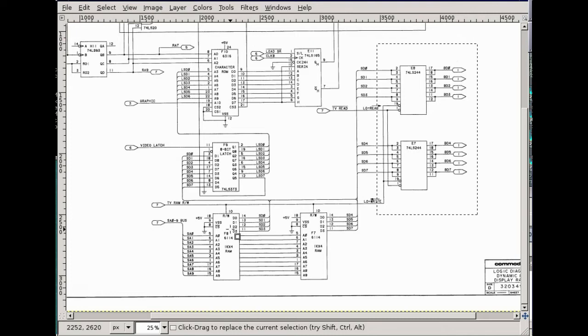Also, because when the CPU is not executing, the random content is displayed fine, and it's not flickering at all. So what are the possible problems? We could have an unstable screen address bus, which is this one.